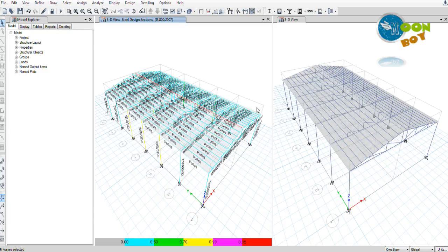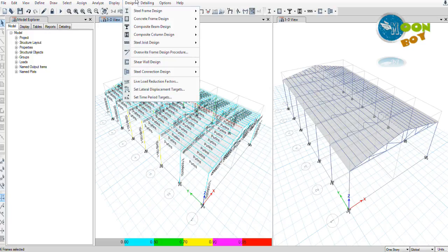We have just provided them for proper provision of the slab at the top. For that we have divided the frame into two sections, but that is not required. So by this you can see that our design is safe and all the members have passed the design, except these six purlins which are not required at that point.